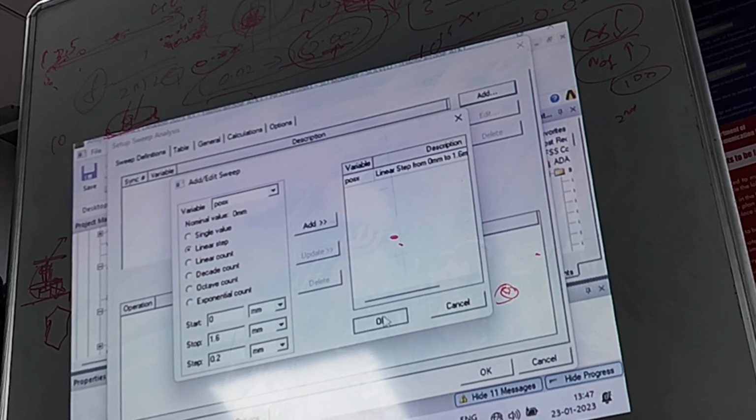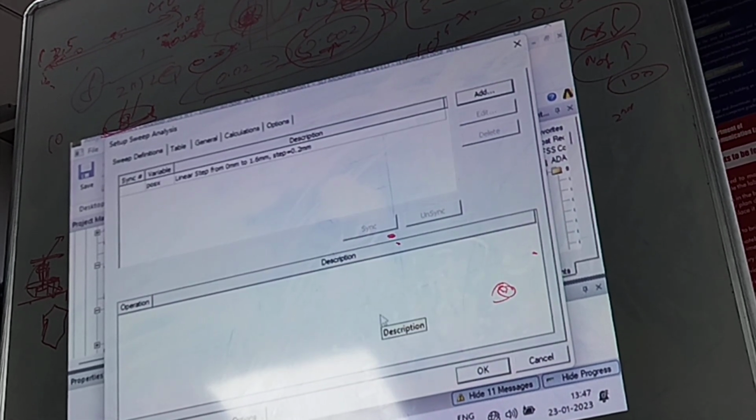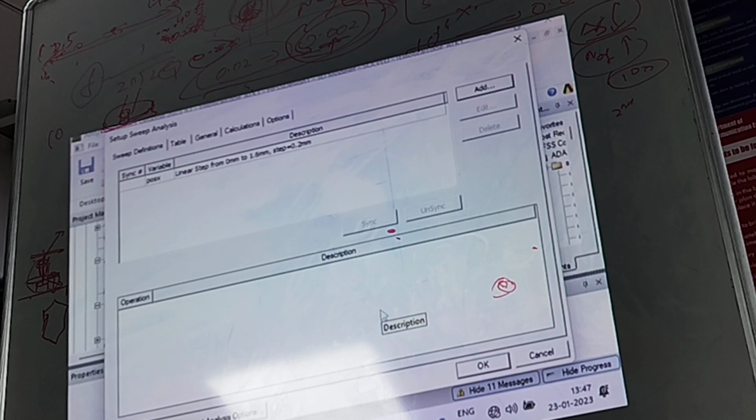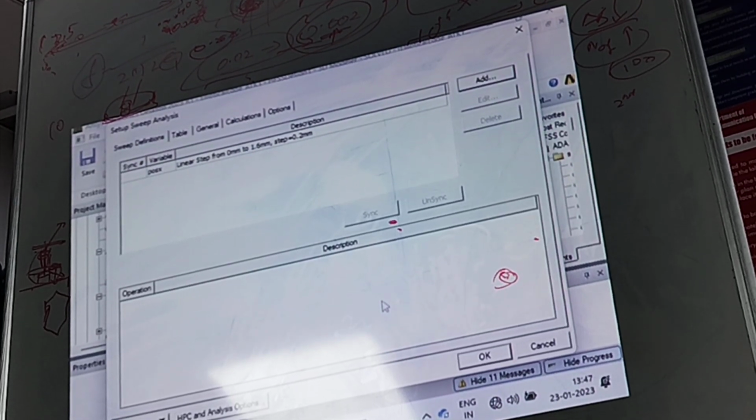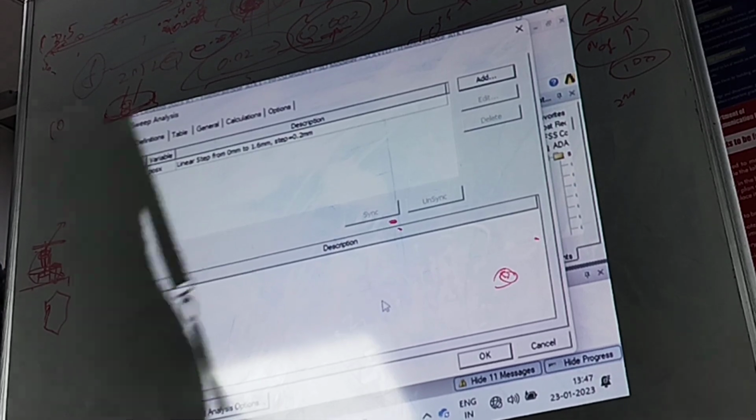So from this we can find out in which particular position my S parameter, that is my reflection coefficient, is very minimal. So at that point I can take it as my matching of 50 ohm is exactly done there.